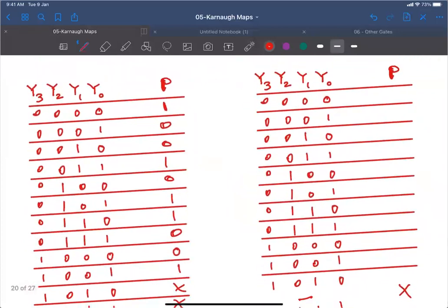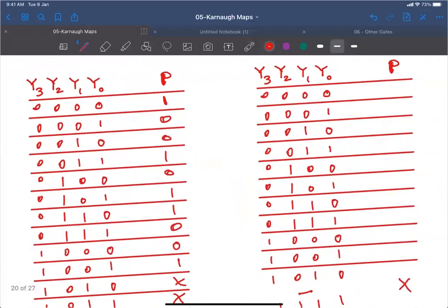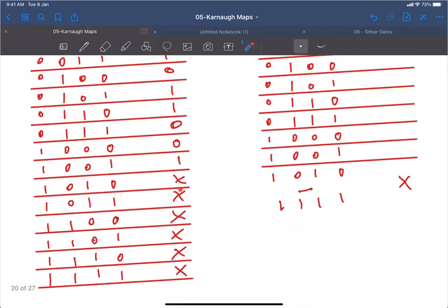You can see that there is a parity bit for all the inputs from 0 to 9, but from 10 to 15, since we are expecting a BCD number, we don't care about the parity here, because we will never receive an input from this range, and if we do, it's the user's problem, not ours.